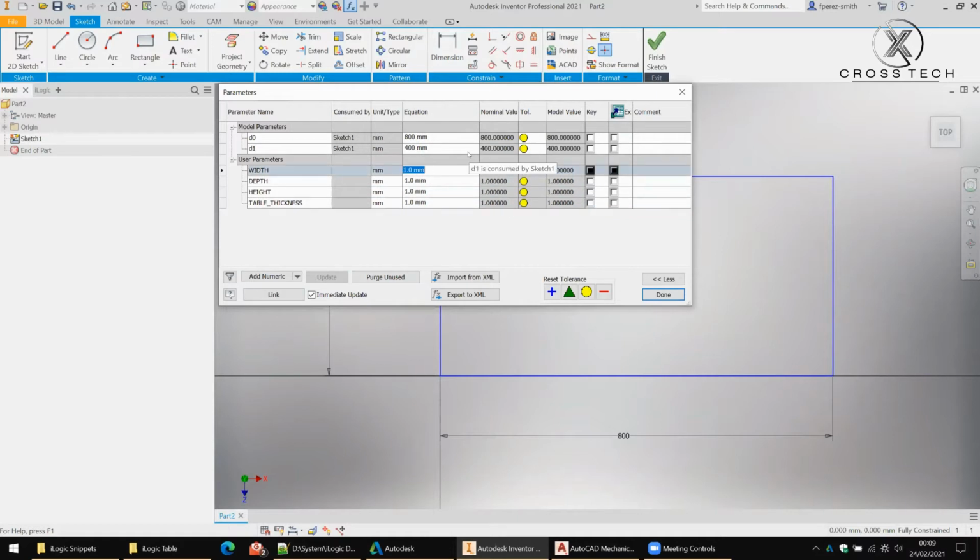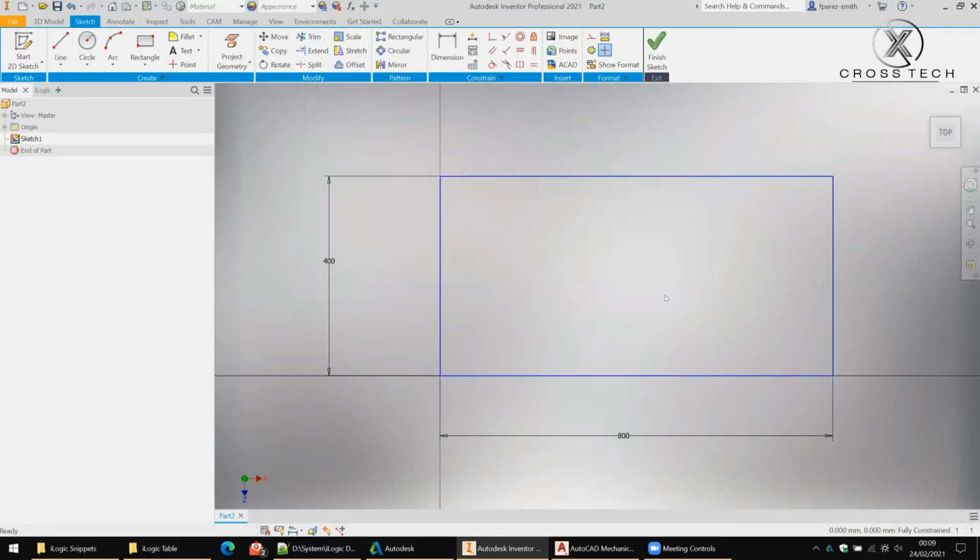Let's make our table maybe 900 wide and 500 deep. And maybe, I don't know how tall the table is. Let's say 450 tall. With the tabletop thickness, let's give it some meat. Let's make it 40 now. Looking good so far.